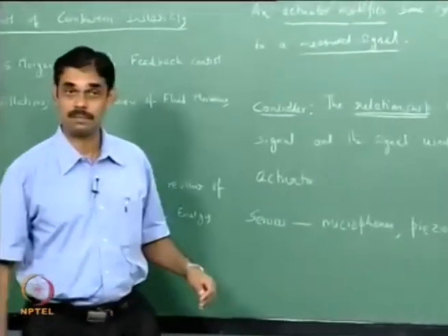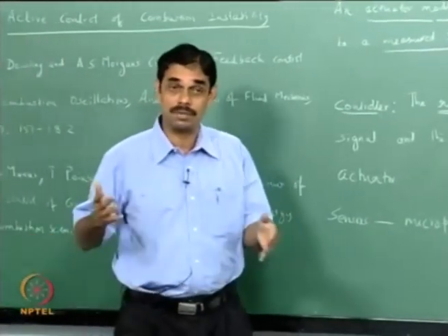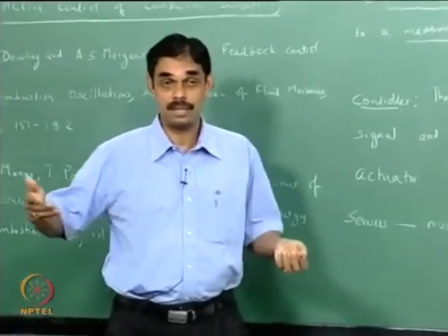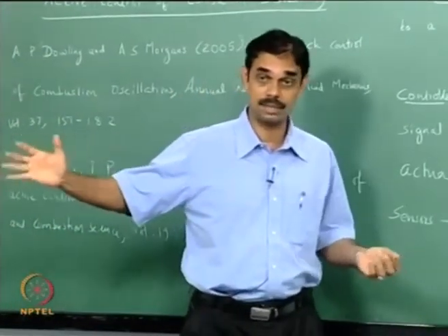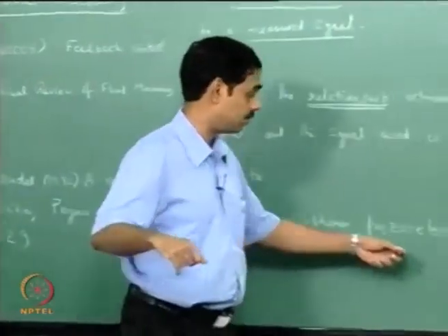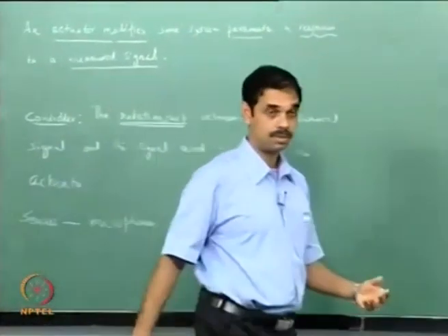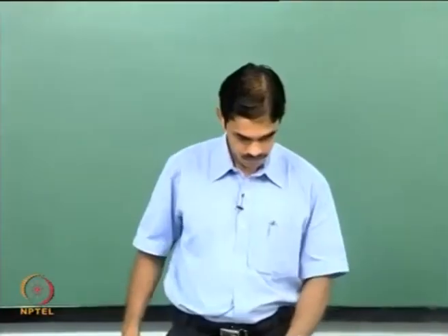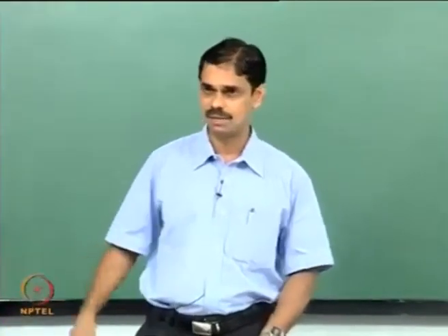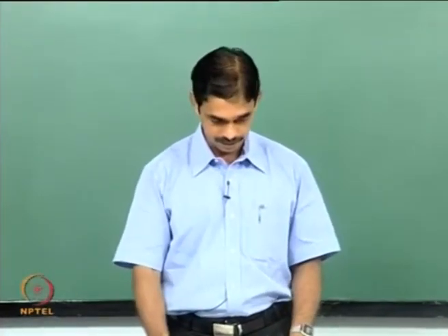We do not have any such problems because we get frequencies of the order of 50, 100 to several hundreds or 1000 hertz. So microphones or piezoelectric transducers both will work very well. The piezo transducers are roughly half the price of the microphone, or one third the price of the microphone.